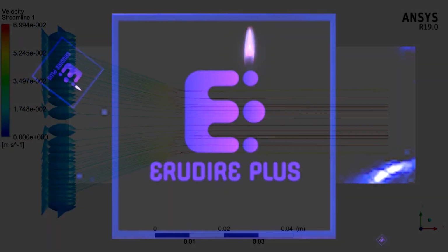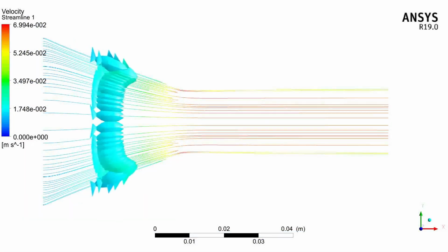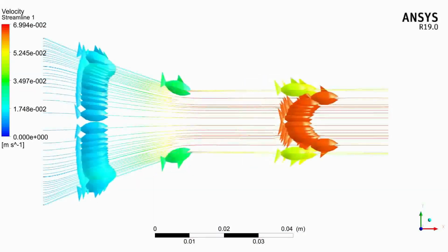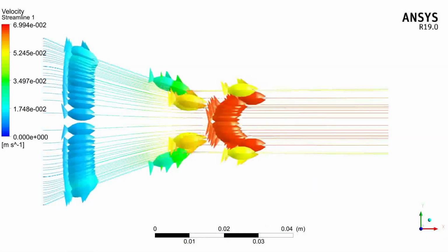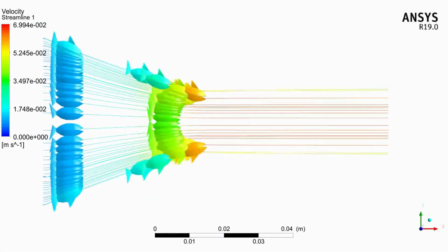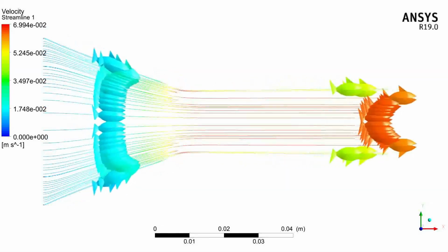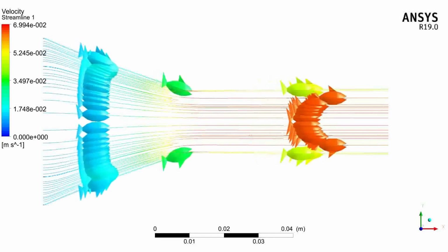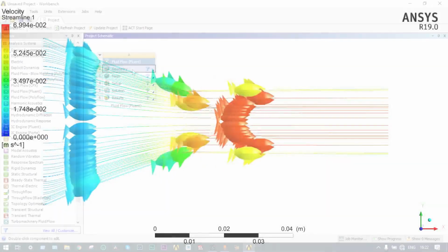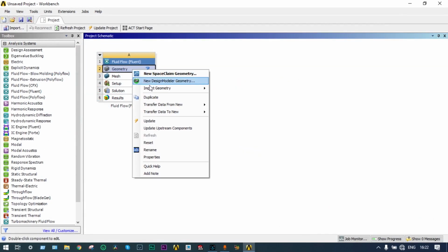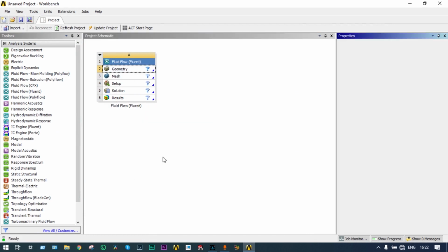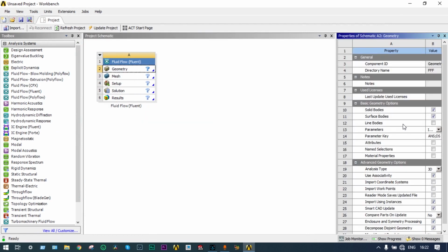Let's get started. Hello friends, today I'll show CFD analysis of a Venturimeter using ANSYS Fluent. We'll consider this one as an axis symmetric problem. First of all, we have to start with the geometry, and let's select the properties to convert the 3D problem into a 2D problem.